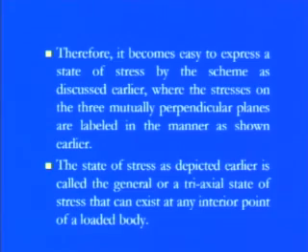So what we need to do here is check how these generalized stresses are formed. The state of stress as depicted earlier is called the general or triaxial state of stress that can exist at any interior point of a loaded body. That is the generalized definition, and it gives a new phenomenon of stress. We cannot say that stress is a scalar quantity or a vector quantity, because in a vector only